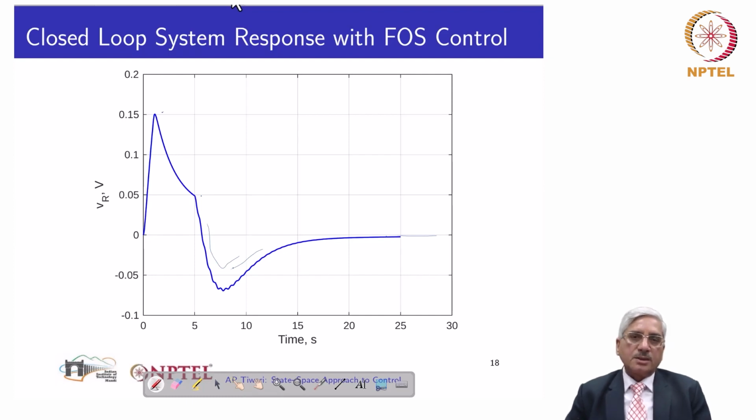So one can consider state feedback and its application to the reactor system. As I said, the system model we have taken is a simple model characterized by only 5 states. An actual reactor system, we should consider the control rod dynamics. We should also consider the internal feedback effects. So a good order of the system will be something like this: 5 plus 1 control rod dynamics, 6 plus 2 feedbacks. So 6 plus 2, 8 order system also one should consider.